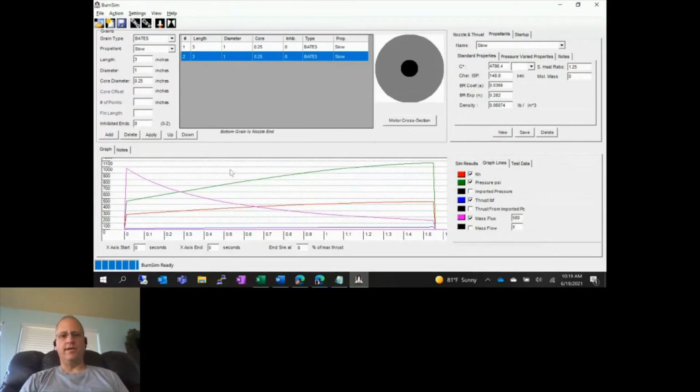And again, that's another propellant-dependent variable. Some propellants have an increased propensity for erosive burning. Others are more tolerant. In other words, with some propellants, when your mass flux gets up to a certain level, it'll impact the burn rate a lot, and with other propellants it won't.